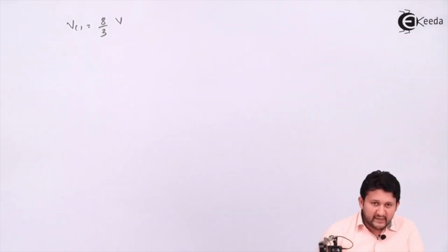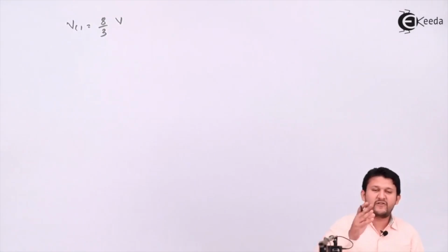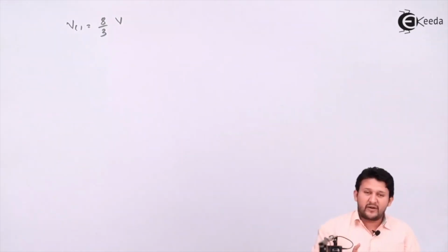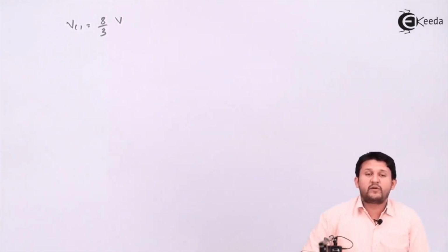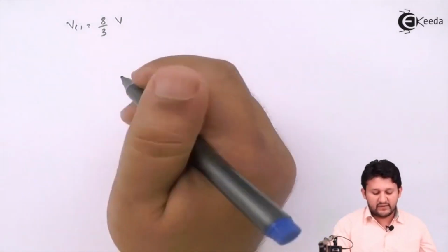So you got how much both the capacitors were charged. That was very important. Because when I start with t equal to 0 plus, it was said your capacitor was in steady state, so I need to replace the capacitor by its voltage. Voltage means how much your capacitor was charged. So let's draw the t equal to 0 circuit.